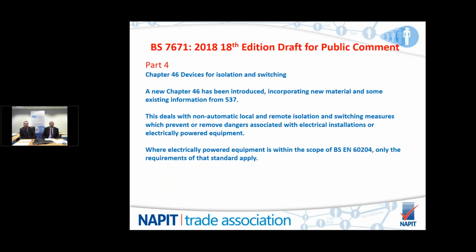We have also a new chapter 46, and this covers devices for isolation and switching. It is a new chapter which has been introduced. There is new material within this section, but a lot of the information comes from regulations covered by 537, which have been moved and brought into chapter 46 to make things more clear on how you cover details of isolation and switching from non-automatic local and remote isolation, which will prevent and remove dangers from installations and powered equipment.